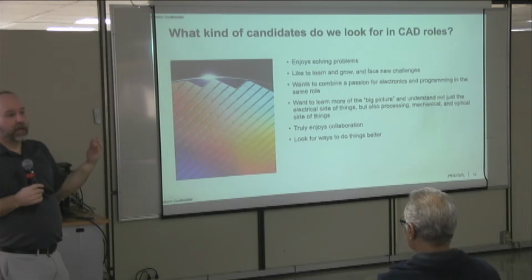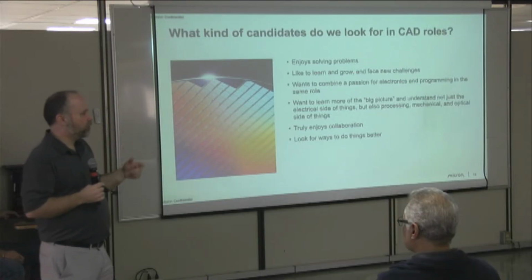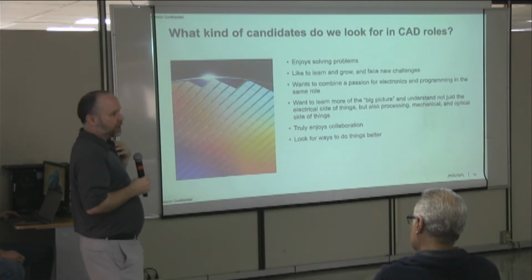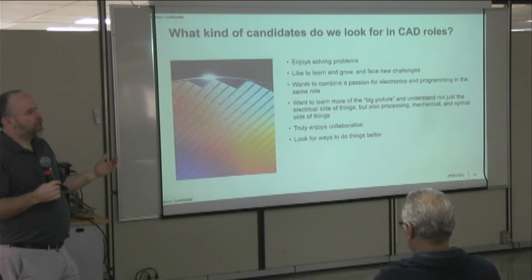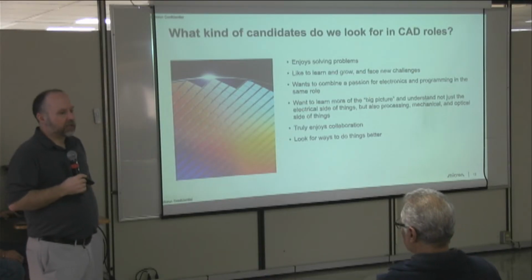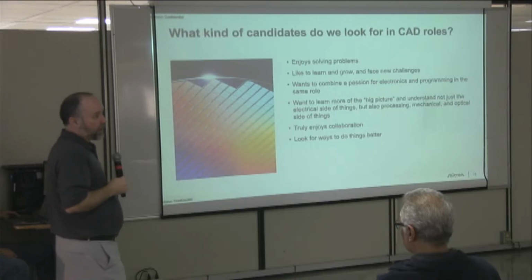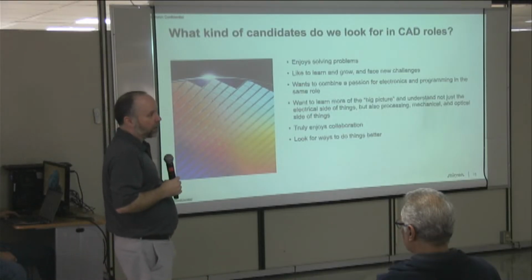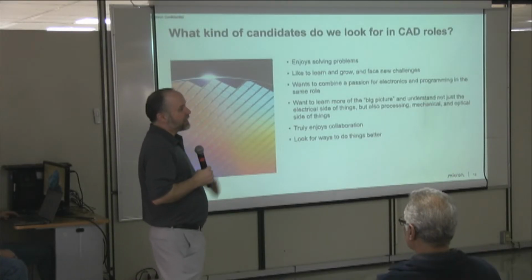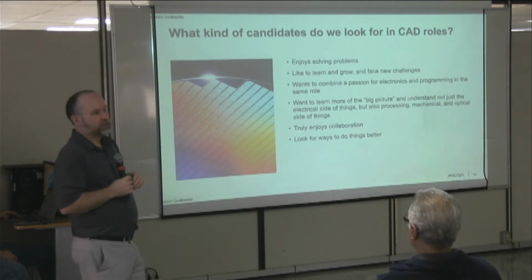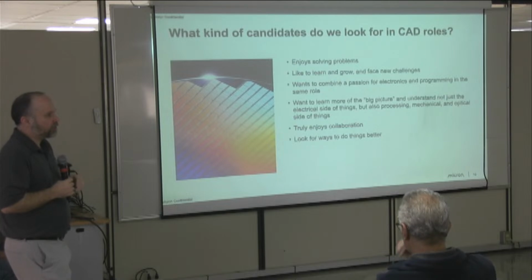And so that becomes a collaborative effort of design, of fabrication experts, of CAD, sitting down and saying, okay, if a neutron can hit any wire on the die, how do you identify which wires are vulnerable, and how do you change your circuitry in a way that if a neutron strikes, it doesn't cause the chip to malfunction? And so those are the kind of problems we solve.